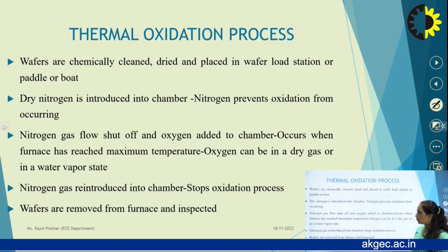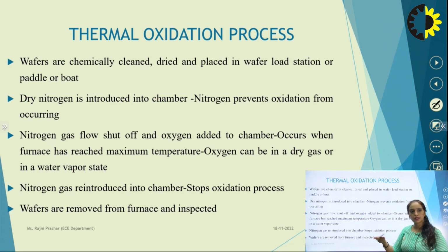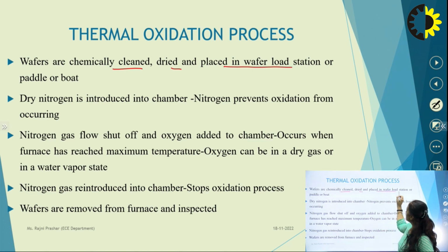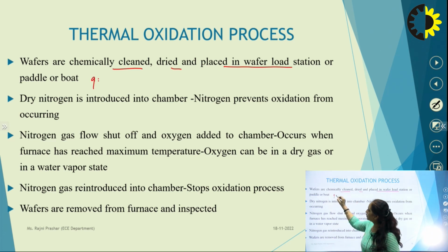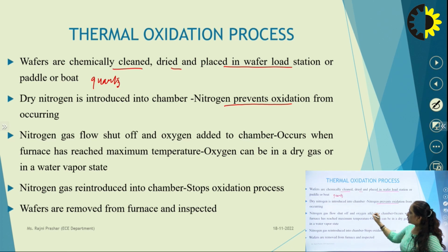Now let us check the theory part quickly. So your wafers are chemically cleaned. Before placing the wafers inside the chamber, we have to clean the wafers. That is the first requirement in any process. So wafers will be cleaned, dried, and then placed in the loading station or a paddle or a boat, right? In this case, we have the quartz boat. Then the dry oxidation is introduced in the chamber, and nitrogen prevents oxide formation, right? So before actually applying the O2 molecule, there should not be any oxidation process. So for that, your nitrogen gas is passed.